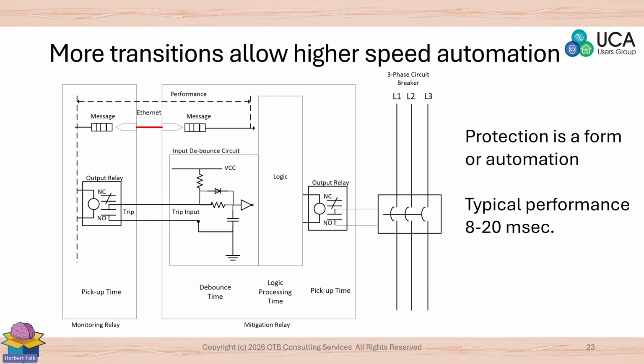And GOOSE actually allows higher speed automation than hardwired logic because of debounce time and output pickup time.